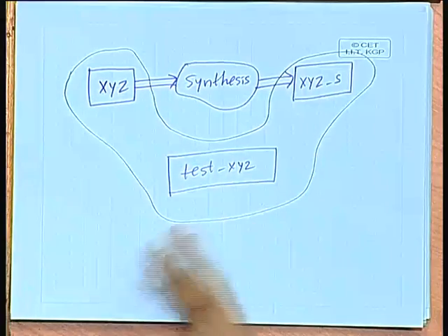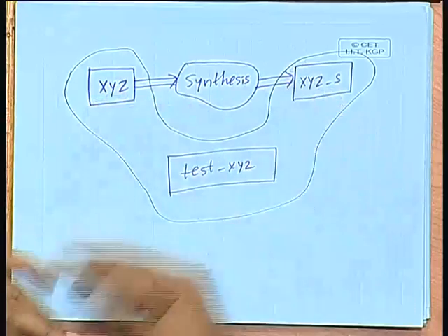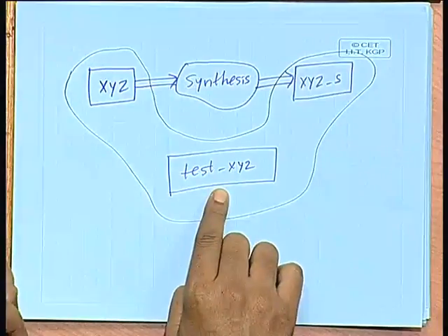Now, as part of your test bench you can do that, you apply this vector here and here, after that you compare the outputs whether they are equal or not equal. If they are unequal, you flag some error message, that also you can write as part of the test bench. But just putting them together at the top level module is just for convenience and modularity, nothing else.